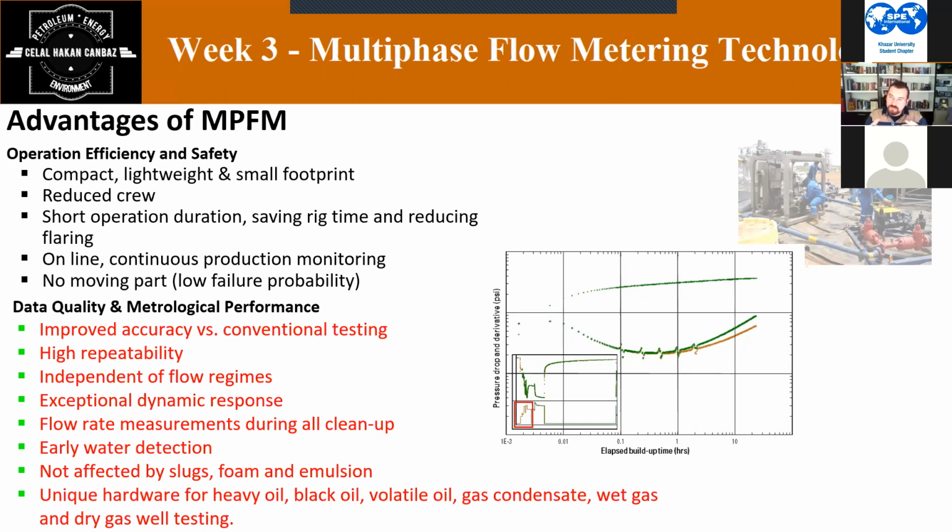Normally the plot of this is a 3D plot. It has 3 Cartesian axes x, y, z, and describes your PVT behavior. We are using in this one just the pressure and temperature behavior, the pressure and temperature phase envelopes. So what it says physically is that in a certain volume of fluid, the pressure and temperature behavior is like that.